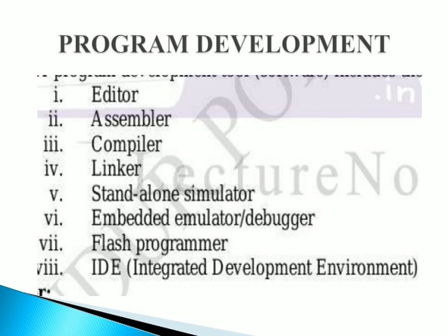IDE, that is integrated development environment. The editor, compiler and linker are usually combined with the help of an integrated development environment. This will keep track of all the files like your source files, headers, linker scripts and so on, which are required for a complete project. The IDEs available for MSP430 microcontrollers are IAR Embedded Workbench Kickstart, Workbench for MSP430, and Code Composer Essentials.